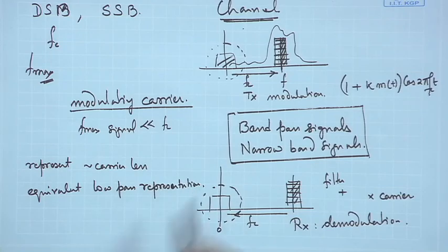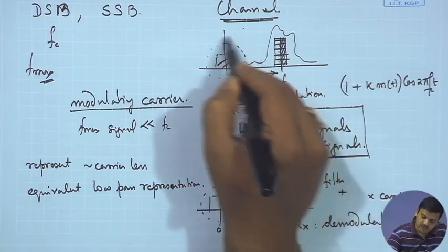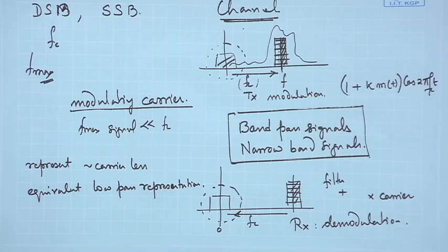In that case we will be removing the effect of the channel and effect of f c, and we will be studying only in the baseband. Now, in this way we would be removing unnecessary need of a very high frequency. If we are analyzing a system, let us say by simulation or other purpose, then also we would be avoiding the generation of large number of samples. For example, if you take a few gigahertz of carrier frequency, then you need to sample it at even a larger frequency going by the Nyquist sampling theorem, and then we have a huge amount of data to process.